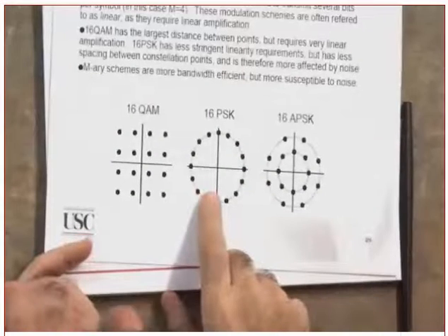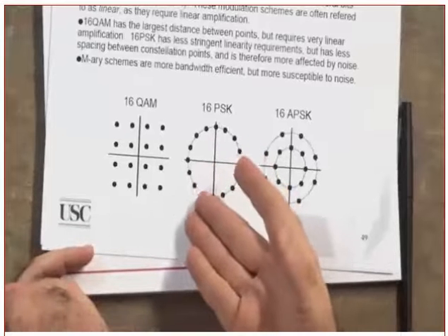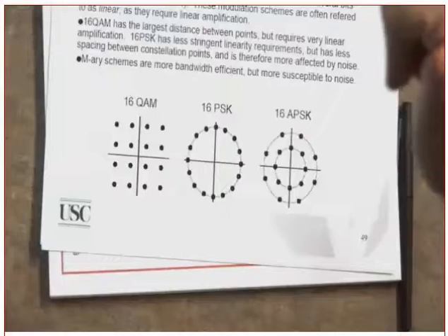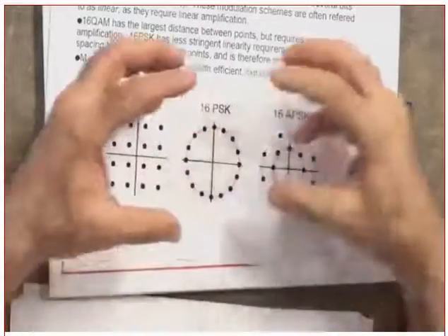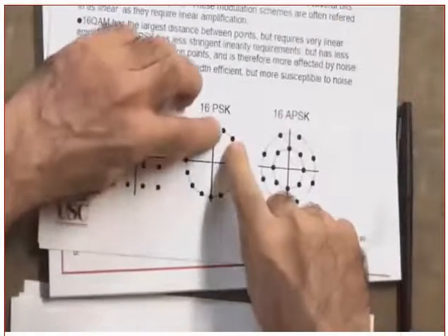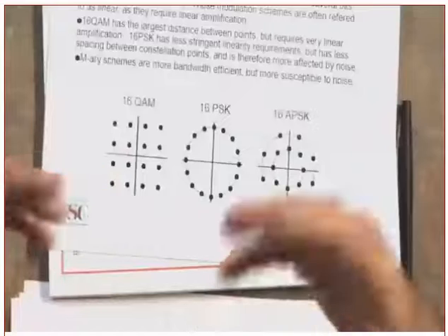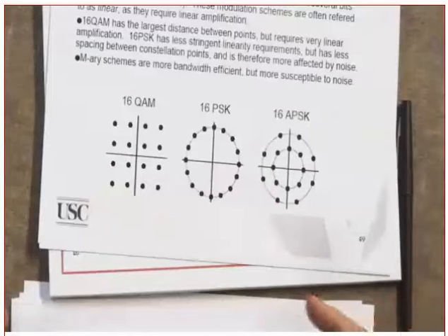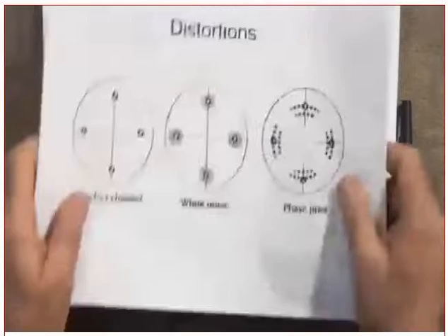Okay, did you understand what I just said? The bandwidth efficiency here will improve to 4 bits per second per hertz. But the probability of error will also go up. In order to maintain the same bit error rate as the QPSK, I need to make this circle bigger and bigger, increase the radius. Will the distance between this one and this one increase if the radius is bigger? That is the whole thing: to try to make the points as far away from each other as possible, to improve the bit error rate. Clear? But that results in an increase in the amount of power.